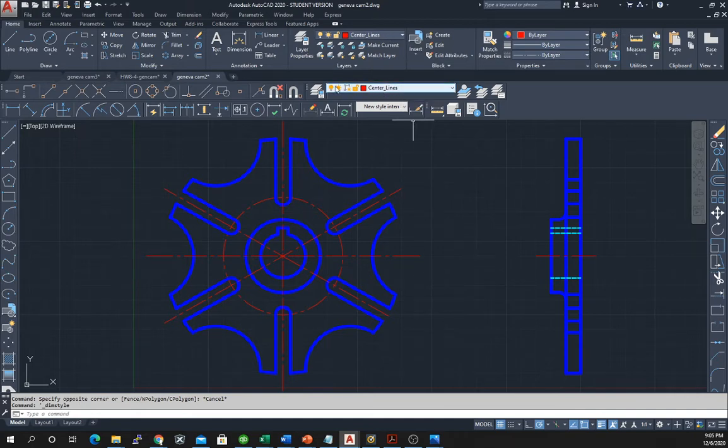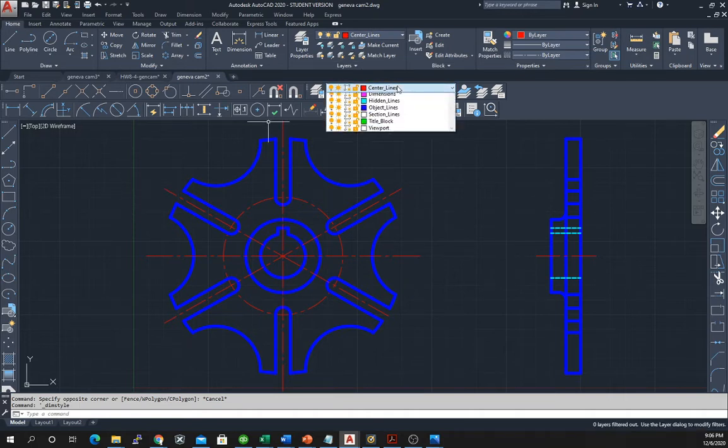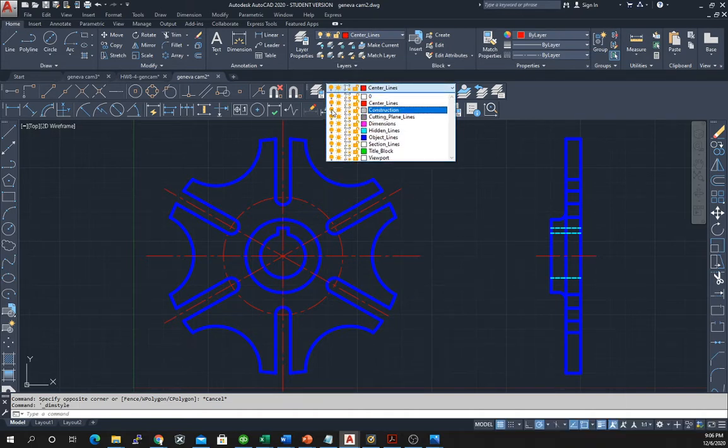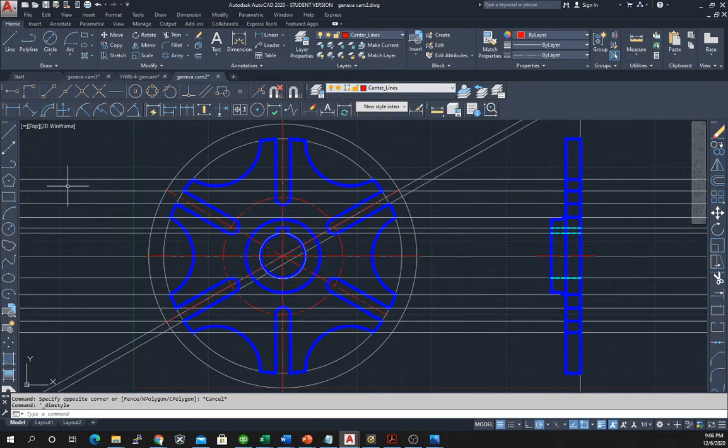Now, while we're still in center line, and if you've left off from where you completed the drawing and we just drew in the center lines, you should still be in the center line position. If not, go ahead and choose center line. We need to add an arc over here corresponding to that 4.5 inch circle. So what I'm going to do first is turn my construction lines back on so we can see all my construction lines, and then I'm going to add an arc.